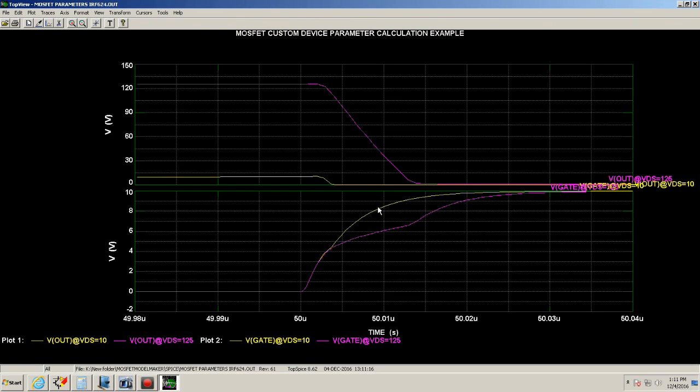So this would be the waveform that you would expect on a MOSFET, I'm sorry, CMOS. But here you got this little phenomena. Okay, you got this little dip, and then this actually corresponds to right there. This should have the same waveform as that, or the same shape. Okay, but this is what I want to bring your attention to. Now you notice that this dip, there's a name to that. It's called the Miller Plateau. Okay, that's the Miller Plateau.